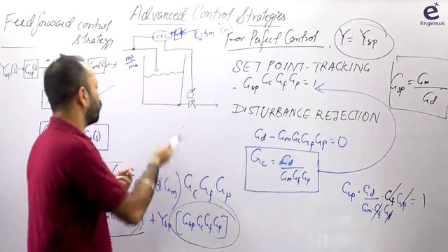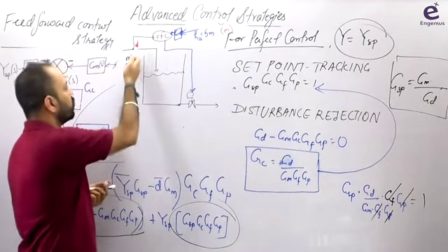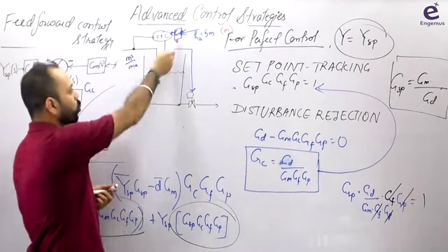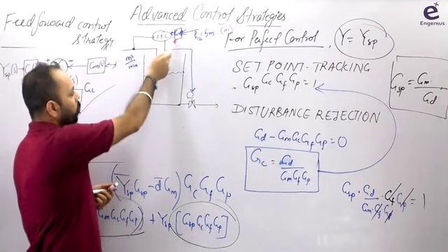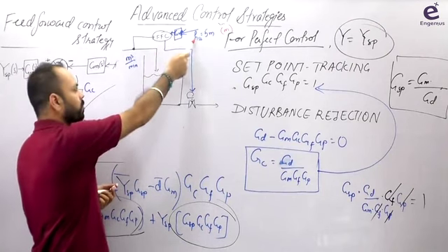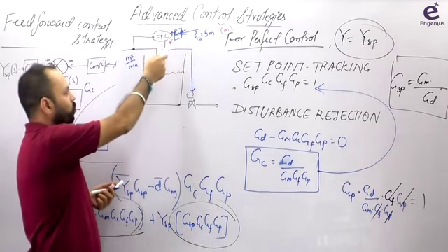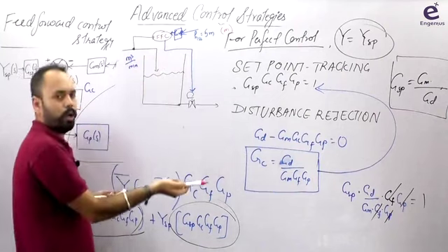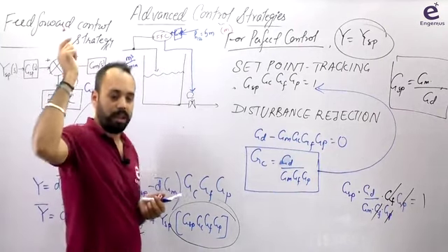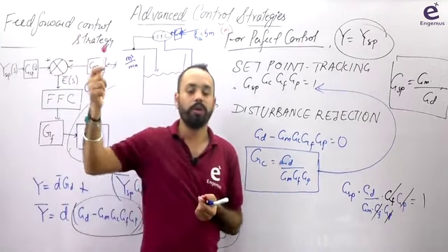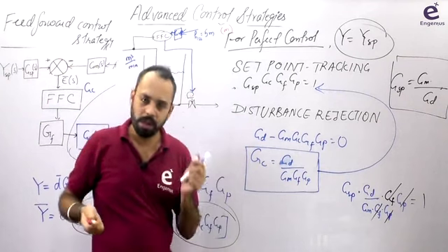But here we are not measuring the controlled variable, we are measuring the disturbance, and we have this model here. Now if this model is inaccurate, then this conversion also will be inaccurate. So the set point going to the controller will be inaccurate. It was the same as the case of the PI controller with the non-unity feedback system. उसमें भी यही हुआ था.